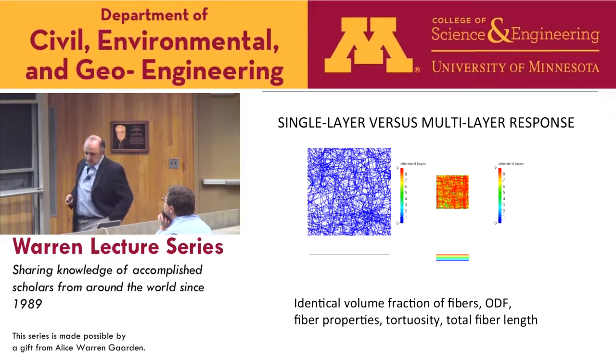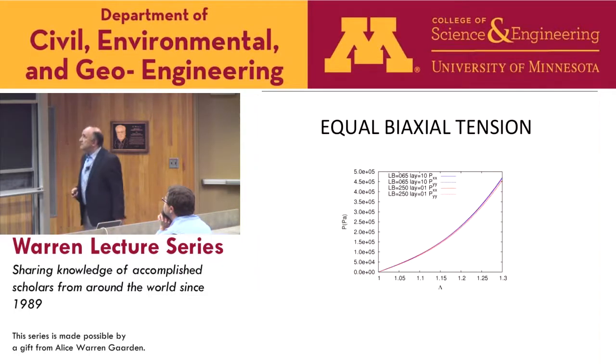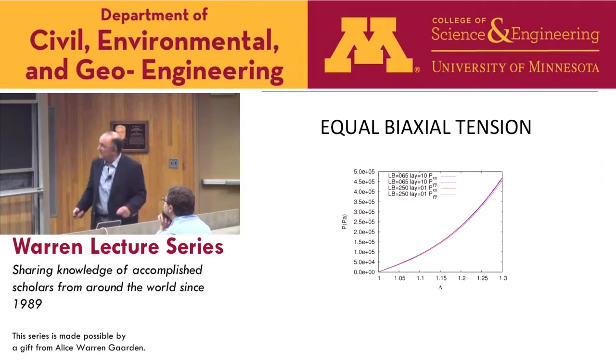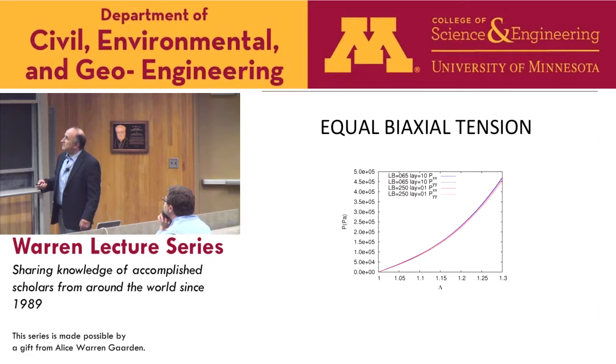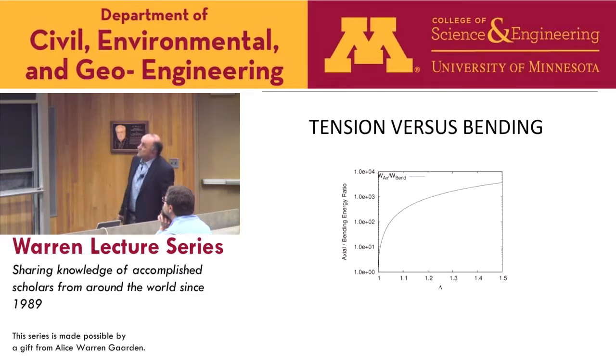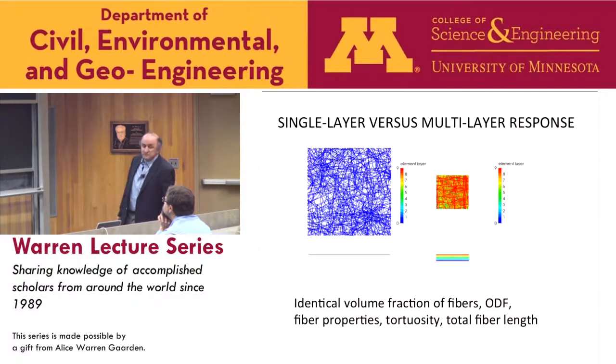And we subjected these things to biaxial strain, equal biaxial strain, and here are the results. It is absolutely clear that we have a pretty biaxial situation here. Isotropic material. We plot stresses, the second Piola-Kirchhoff, PXX, PYY, and all curves collapse. So basically, A, we have an isotropic story. B, the difference between this case for a monolayer versus 10-layer is immaterial. We're getting the same response. We tried other loadings, and that's also true.